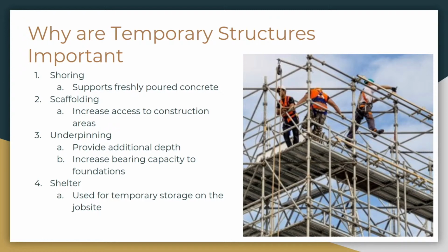In addition, the loads a structure must endure during construction are often higher than its design capacity due to the heavy equipment used in the building process. So additional supports are needed to carry these forces as well. Shoring is an economical and effective solution to solving this problem.